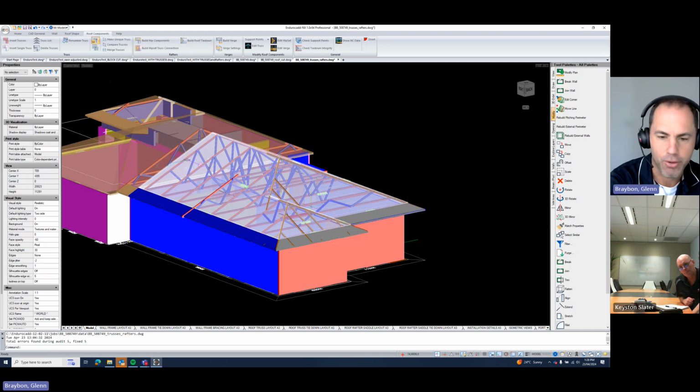Yep. So what we want to do, we understand that if we allow the user to ignore that and it gets to the machine and it won't roll, that is a big problem. We want to fix those issues before they become a severe NC data error and the user can't roll. So what we want to do is fix that INS or RF punch code that's outside the frame perimeter. We want to fix that in EnduroCAD so you don't get that error, which is what we're going to do in this case.